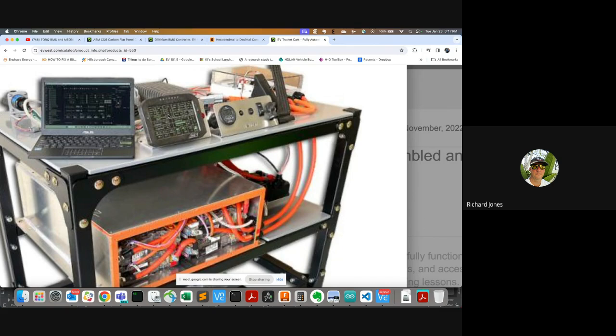And then with the AEM, if you have these magic DBC files, you don't need to look at the bits and bytes of the individual CAN message. You can go select cell 17 or temperature 23 or whatever, and then pop it up on the display without having to get to that lower level. So for most people, that's the value of a display like that. While it's rather expensive, it does save you a lot of time and not needing to know every last bit and byte down on the CAN bus.